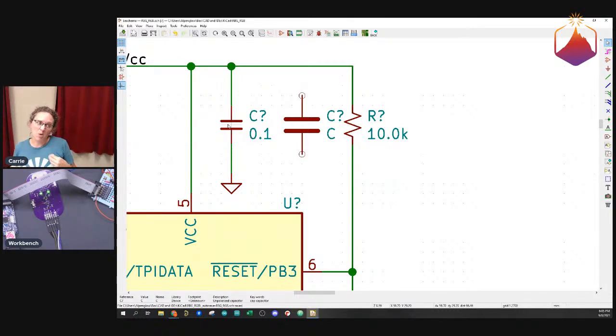But it's a small board, and 22 microfarad capacitors are more expensive, so you just put two 10 microfarad capacitors together, and that makes 20, which is close enough. So when you have a bunch of them together, I can squish in way more of these capacitors than I can of those, all in a nice tidy row. So yeah, the default one is terrible.